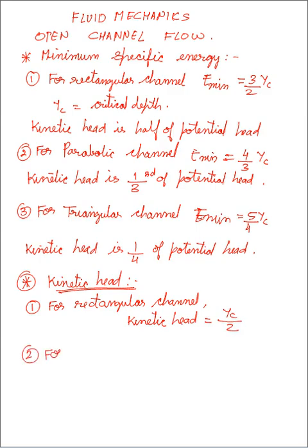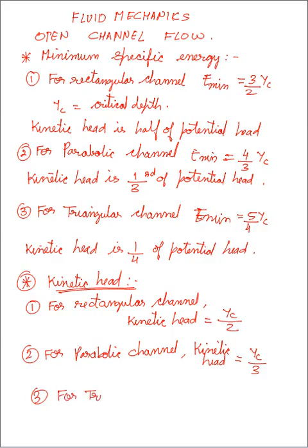For a parabolic channel, kinetic head is equal to YC by 3. And for a triangular channel, kinetic head is equal to YC by 4.